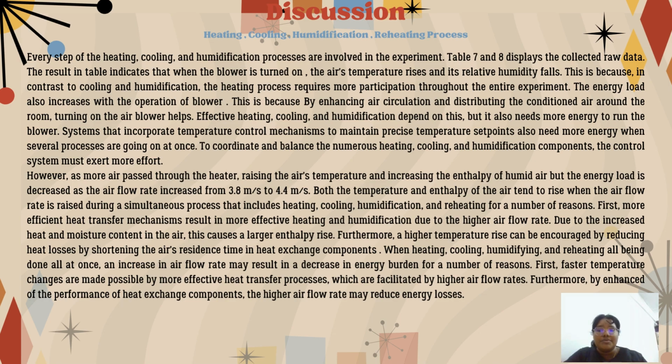When heating, cooling, humidifying, and reheating are all being done at once, an increase in airflow rate may result in a decrease in energy burden for a number of reasons. First, the temperature changes are made possible by a more effective heat transfer process, which is facilitated by a higher flow rate. Secondly, by enhancing the performance of heat exchange components, the higher flow rate may indicate less energy requirement.